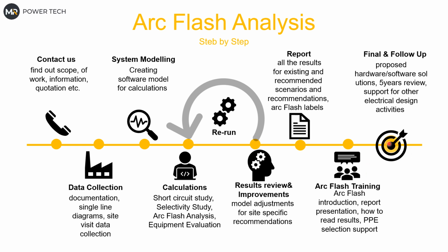And at the end we have a follow-up. So we have a model, we have everything done. Every 5 years maximum we have to update it, which means every 5 years or every bigger modernization on site. So if we move the switchgear, change some machines, maybe update the transformer to a different one, change the protective settings, etc., then we have to update the calculations to have the real data.